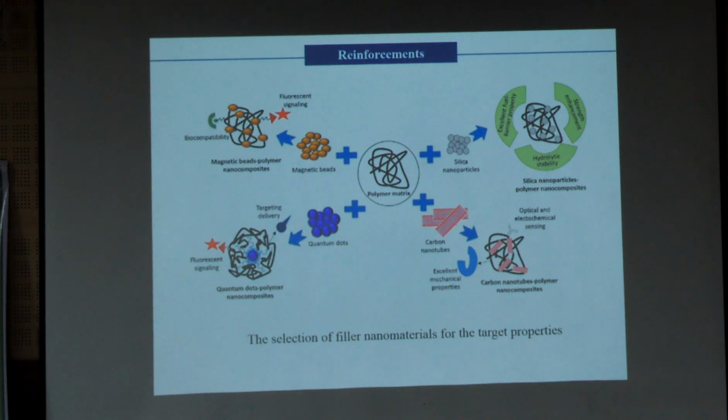Yes, damping property. So here the damping coefficient should be more, and it should absorb more energy but should not transfer to the other medium, right? So like that, depends on the applications, we select the nanoparticles and we reinforce the nanoparticles into the matrix, and then we manufacture the final component.